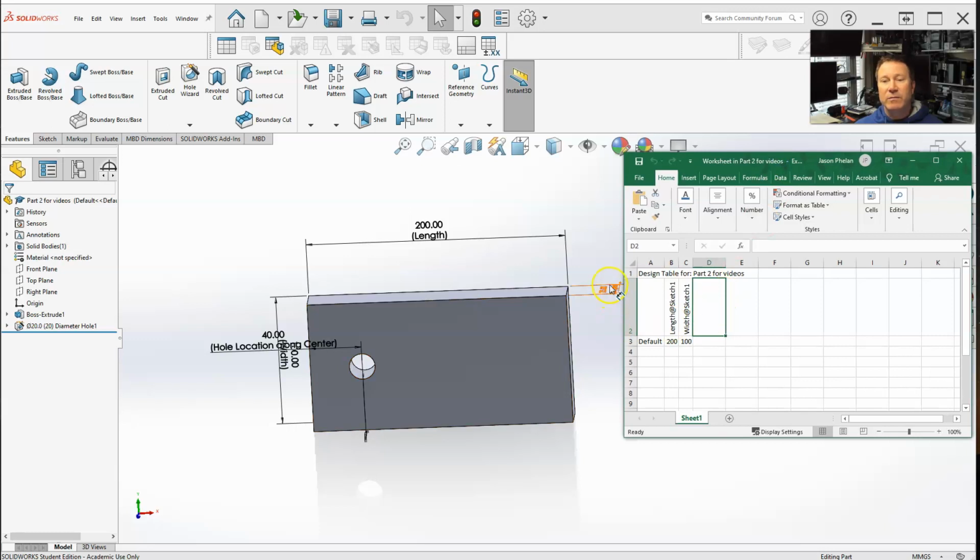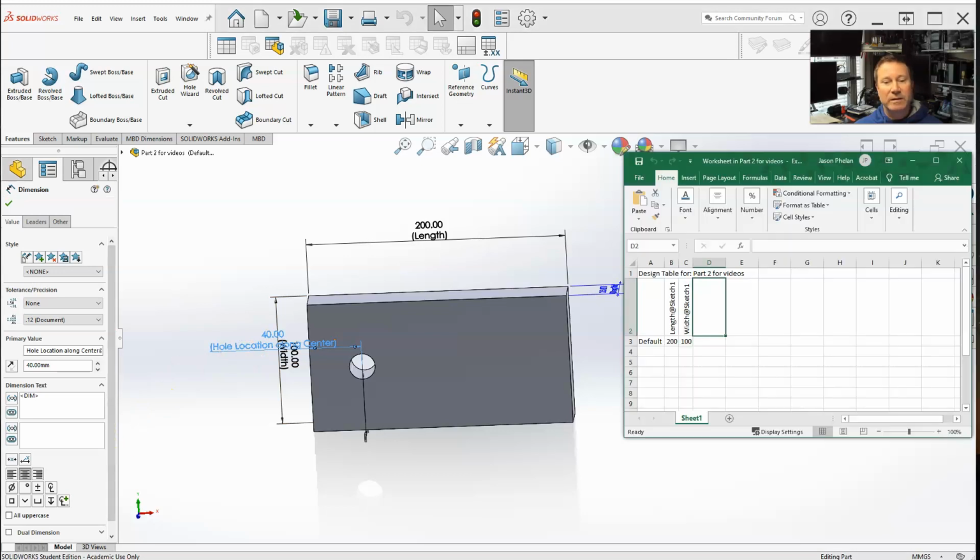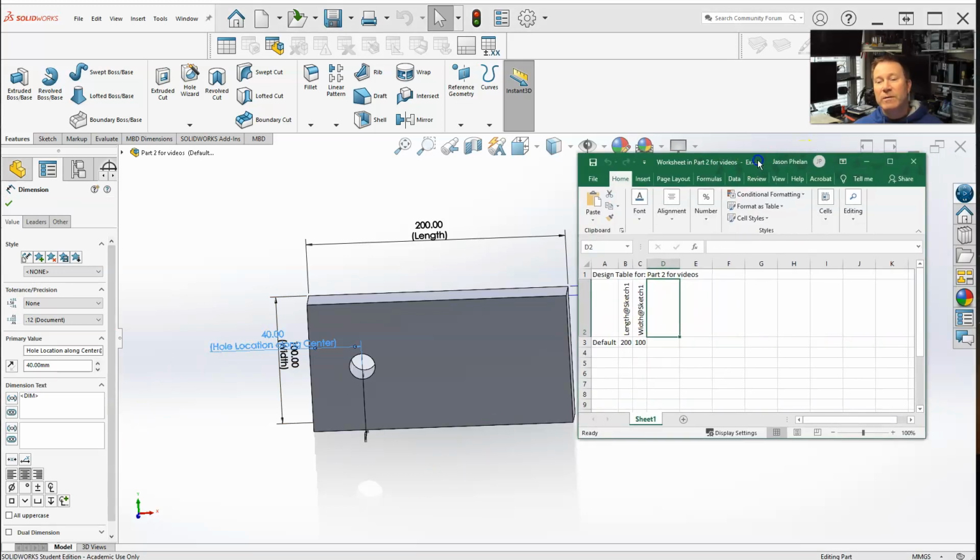Let's say, does this one allow me to add more? Let's see, location, whole location. No, it doesn't. So with the auto create, I selected those two, and this is the second column. This is where your dimensions or your features will pop up. I recommend typing in family. That way, if you ever need to modify this, this is the family function. This is where all of your dimensions and features will be listed on row 2. I'll go over how to modify the charts after that.